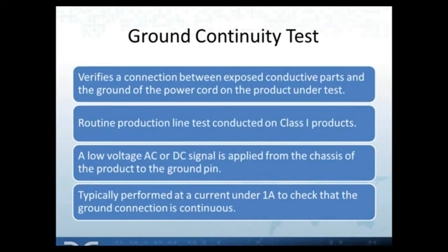For example, when the insulation of a product develops a fault between the line circuit and the exposed metal parts, the ground conductor provides a path for the dangerous fault currents to return to the system ground at the supply source of the current. If the ground circuit is of a low enough impedance, the current will circulate through the ground conductor of the equipment, enabling the circuit breakers or fuses to open.